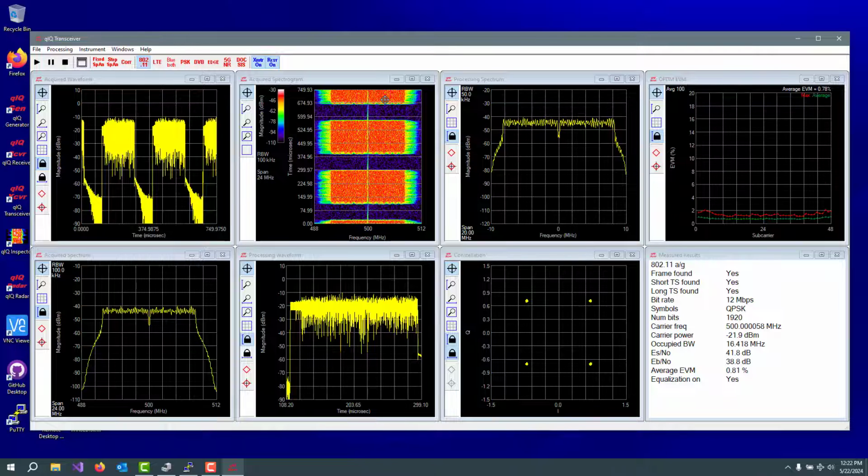And when we do a demod for 802.11, we go in and capture one of these frames. So we have to trigger and search through the data and find a frame. So here we looked through the data and we found a frame of data to process, and this is the spectrum of that data that we are actually going to process and do the demod on. So the windows are named Processing Waveform and Processing Spectrum. Then we go through the whole demod of this.